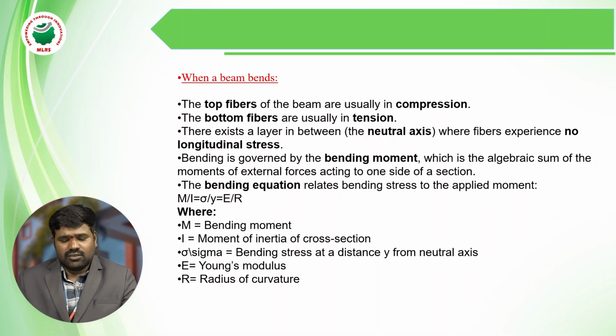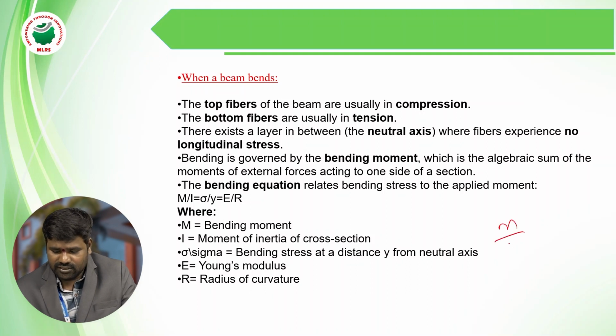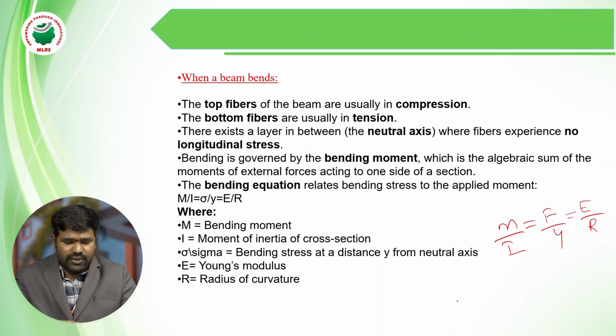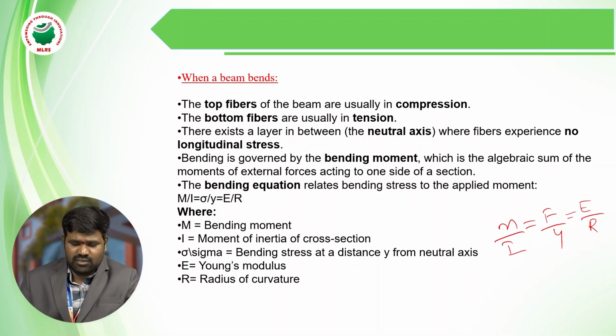Bending is governed by the bending moment equation M by I equals F by Y equals E by R, where M equals bending moment, I equals moment of inertia of cross section, F equals stress, E equals Young's modulus of elasticity, R equals radius of curvature.